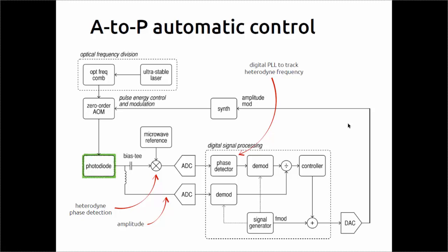We do the obvious division of the phase by the amplitude to get the amplitude to phase conversion coefficient. We implement a controller that acts on the acousto-optic modulator to keep the power emitted by the optical system at the magic working point where the amplitude to phase conversion is 0.